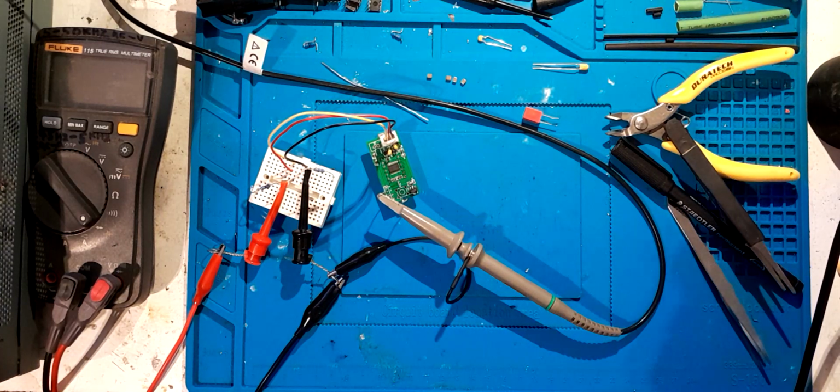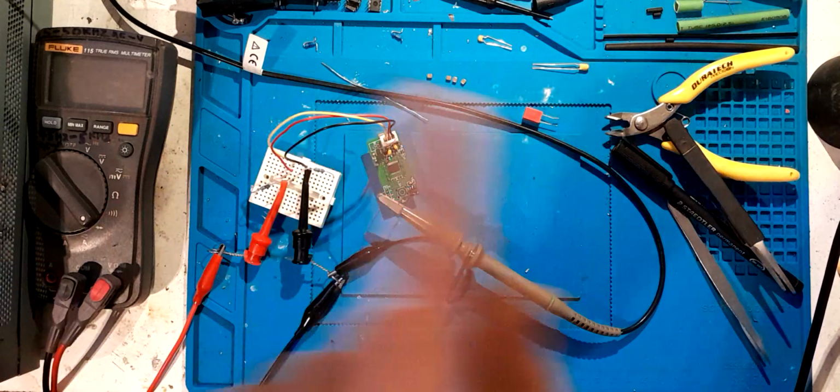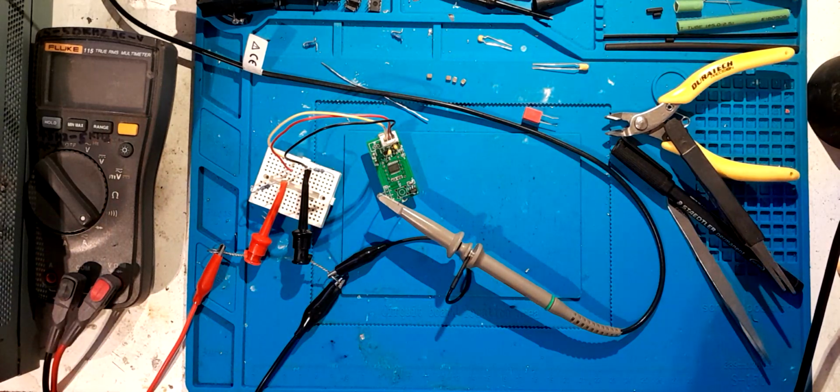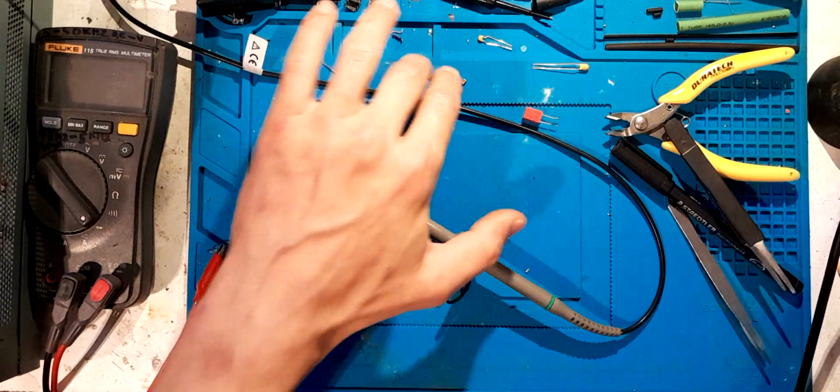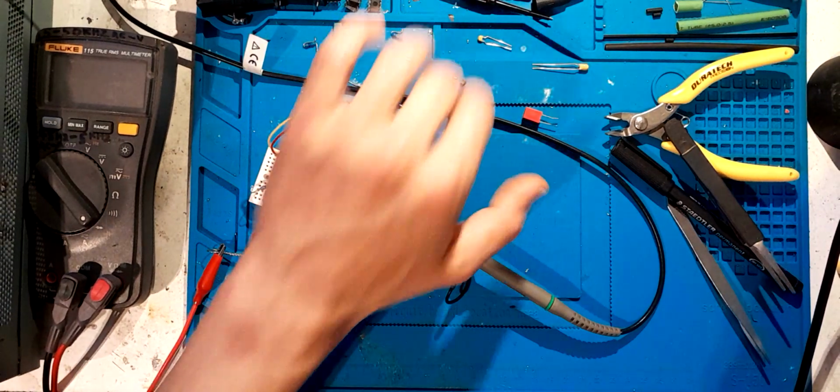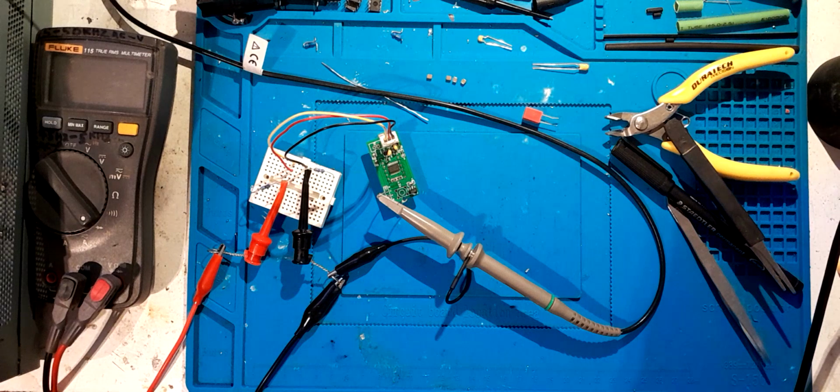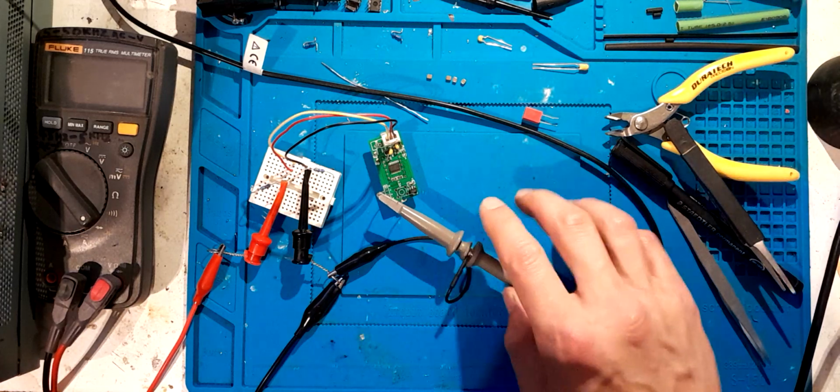I can see like a snubbed waveform that's a little bit smooth, but it still has sharp edges and the right rise and fall time to make it look like a good square wave transitions. So I'll leave that as it is. Alright, well, I'll take that off, stack them on there, and we'll go from there.